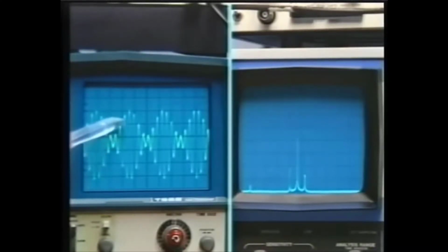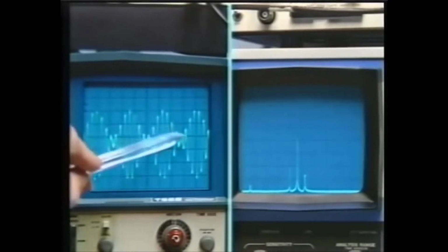You can see the sinusoidal modulating shape at this point. Let me switch that to a triangular shape. And again, it's a little hard to sync in both the modulating signal and the carrier, so you see the carrier kind of wandering by, but there it is.